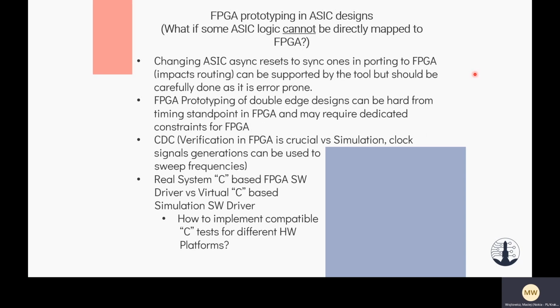Another consideration area is the option to replace asynchronous resets that are probably implemented in original ASIC designs with synchronous ones. In most FPGA platforms, it is possible for the tool to do it automatically. The need for doing this is that you can drastically improve the routing, releasing some routing resources to connect more important, more timing critical paths in your design. So you improve routing, but unfortunately, by changing the reset architecture, your design is no longer logically equivalent.